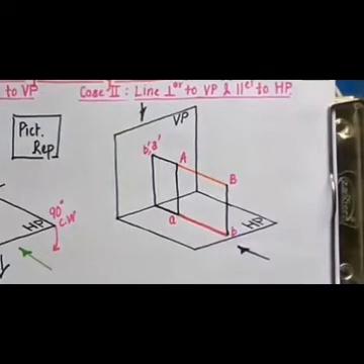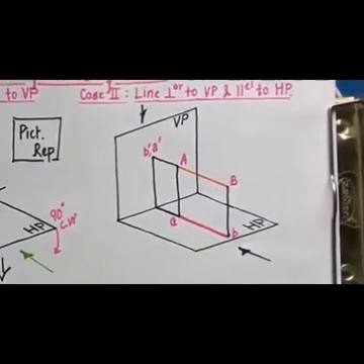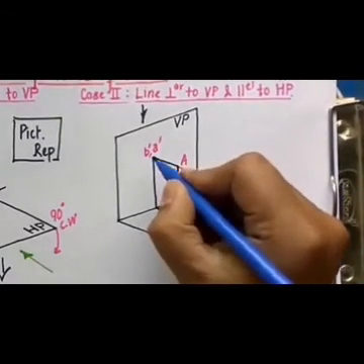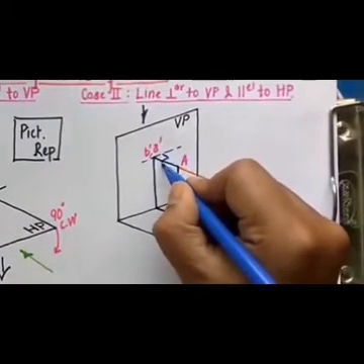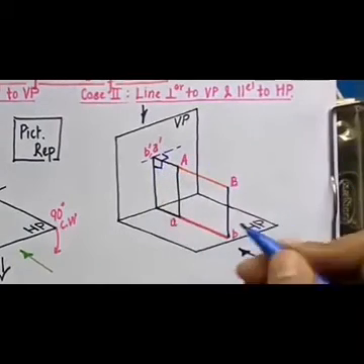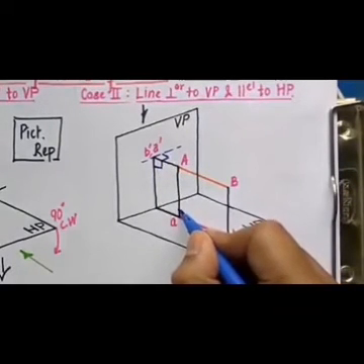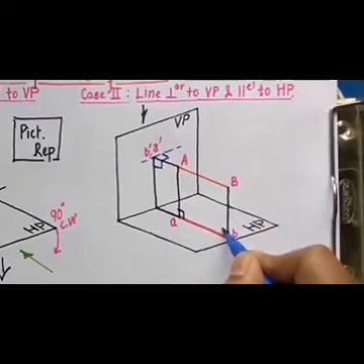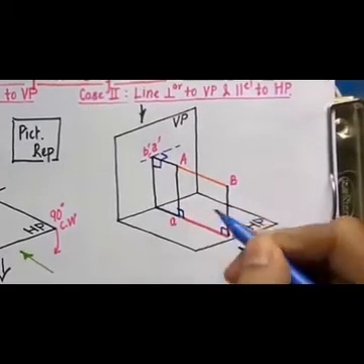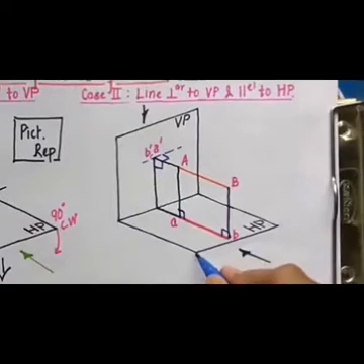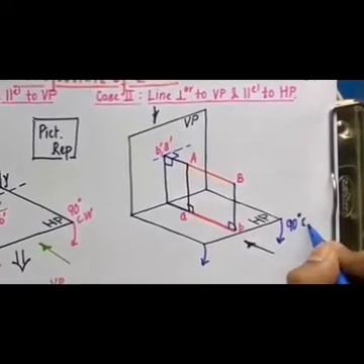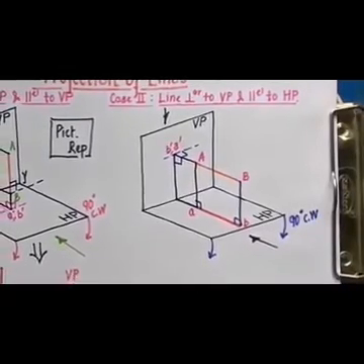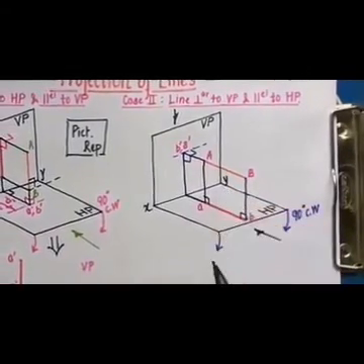As I've already told you, this line makes a 90-degree angle with the vertical plane. You can clearly see this. This is what you call the right angle with the vertical plane. Even here the projector always makes a 90-degree angle. And again we need to do the same thing. We need to rotate this 90 degrees clockwise, and on doing so we'll have this XY line in the orthographic view.